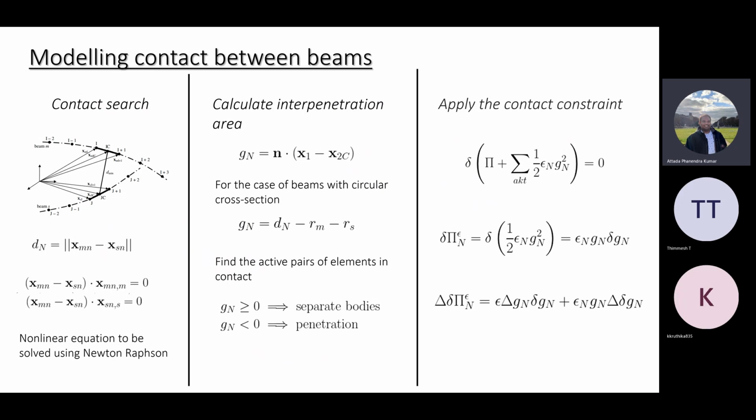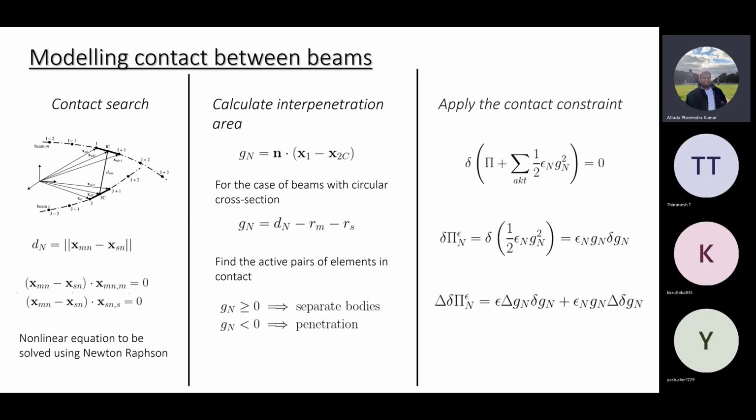There are two very popular ways of solving an optimization problem, which are penalty and Lagrange multipliers. Lagrange multipliers lead to additional variables, so if the stiffness matrix is there, we'll have a 0 element on the diagonal. This will cause complications while solving, because the 0 on the diagonal will lead to a different solver. We'll have to use a different solver or modify the stiffness matrix in such a way that we can use the solver. This leads to complications. So people usually prefer the penalty parameter.